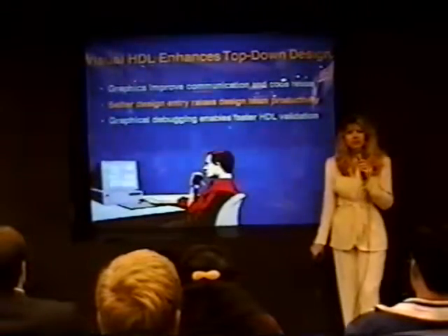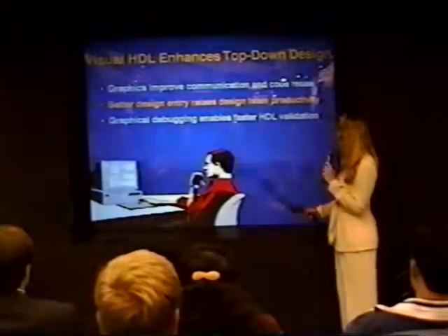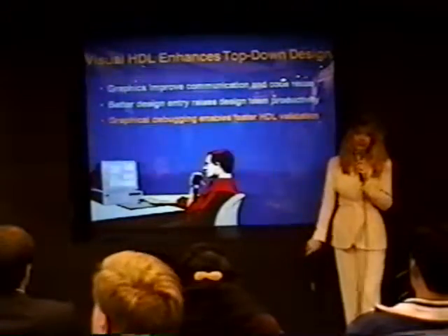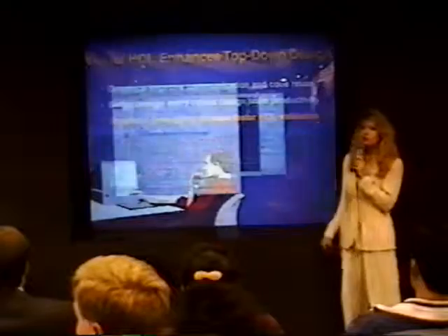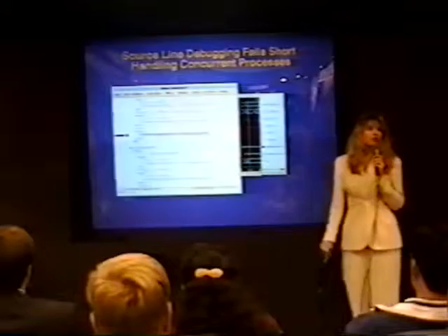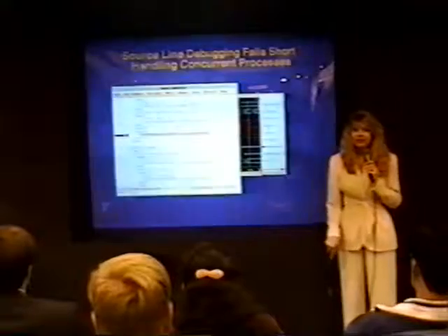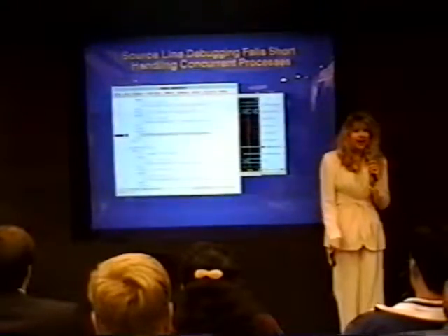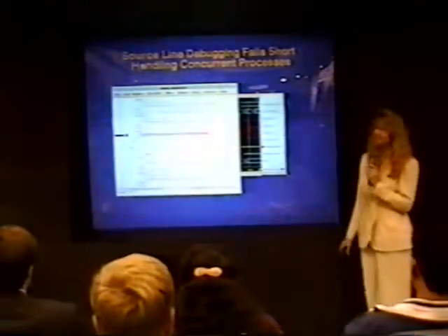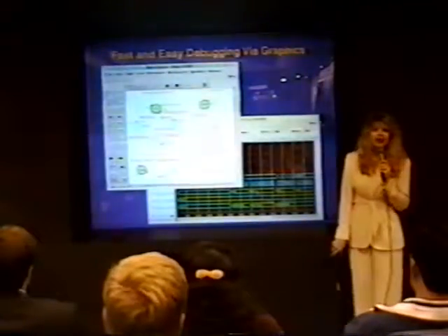Now perhaps Visual HDL's most valuable asset is its graphical debugging. With Visual HDL, bugs once concealed are now revealed. Tools like source-level debuggers and waveform displays are great when you work with sequential code, executing one line after another. But HDL was designed to model concurrency, and debugging concurrent code in a source-level debugger can be a nightmare. Visual HDL's debugging facilities were designed to handle these issues.